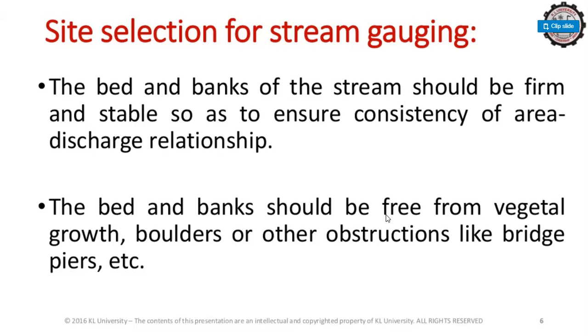There are four criteria in selecting a site for establishing a stream gauging station. They are accessibility, adequacy, stability, and permanency. The station should be accessible under all conditions, particularly during floods. The station should be able to cover the full range of discharge which may occur. The stage discharge relation at the site should change with time as little as possible.